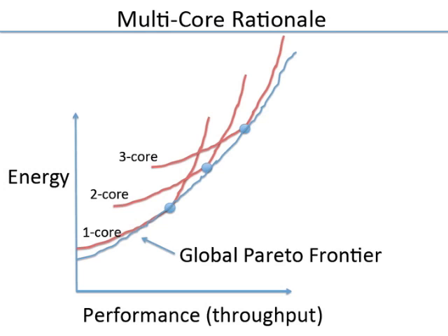As we said, critical path you want to reduce. Highest performance processors have 12 to 14 FO4 delay, fan out of 4. You want twice the throughput. So you say I'm going to go to 6 FO4 delay. So you see the number of flops you have, right? Every 7th gate, huge number of flops, huge power.